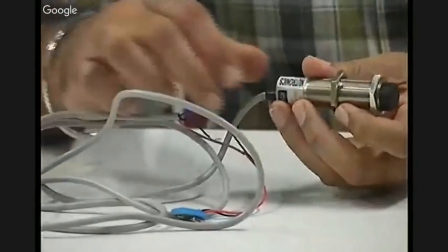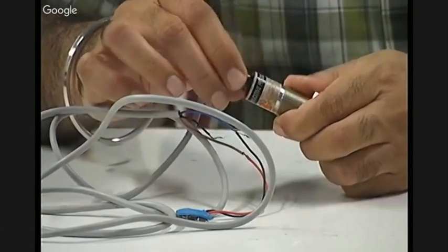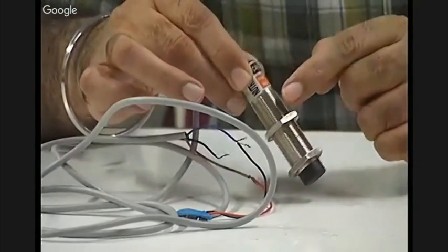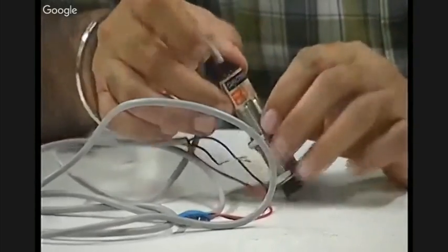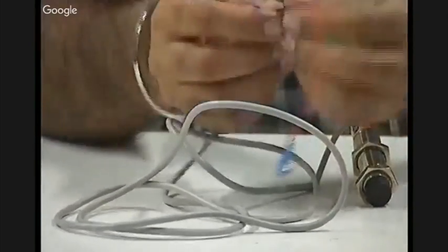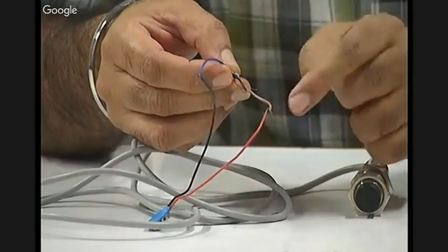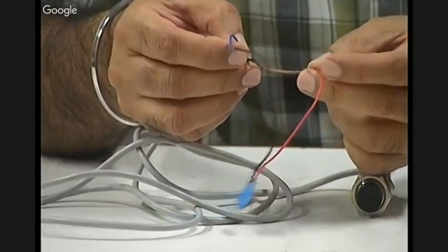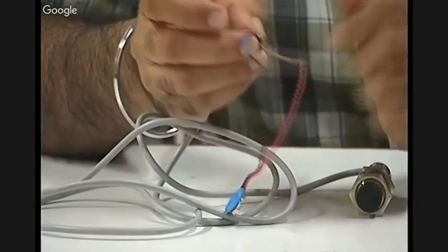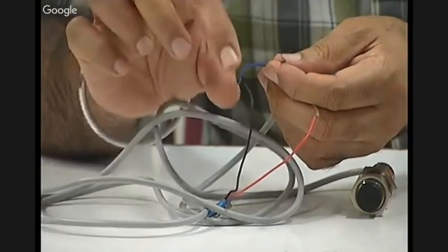So this is the same sensor that you are seeing on the screenshot, right? You may be able to see it is written here capacitive sensor, and on this label all the information is provided about the kind of the sensor and where to connect the inputs, from where to take the outputs. That is too small, may not be visible on the camera. So this sensor has 3 wires: brown, black and blue. Brown is for giving the positive, blue is for giving the ground, and we can get the output on the black. So as I said, to any controller at the appropriate input port, we will attach the black wire and the blue will go into the ground.